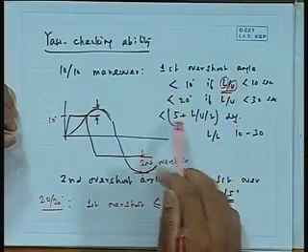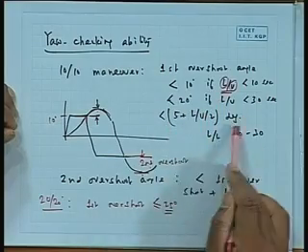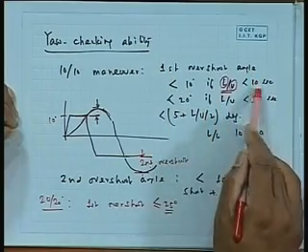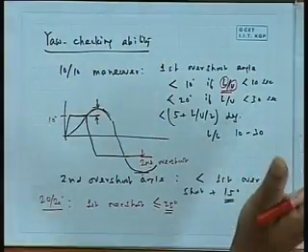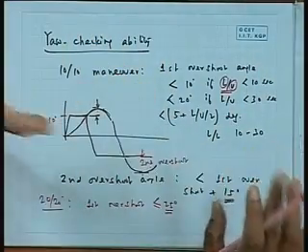What they are trying to say is that for the 10-10 maneuver, which is more logical, normally you do not maneuver with a very high rudder angle. For the 10-10 maneuver, the first overshoot and second overshoot angles are specified. Your ship must maintain that criterion. The first overshoot must be something, and that criterion is related to length and velocity. You can always work it out by L by V. It is between 10 to 20 degrees, and in between, the formula is a straight line interpolation between the two. If it is less than 10, so much; more than 30, so much; and between 10 to 30 it is just a linear interpolation.